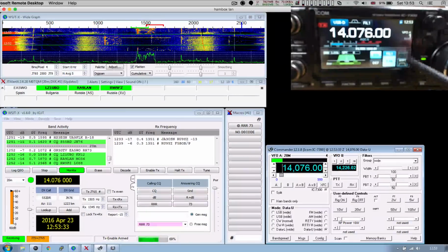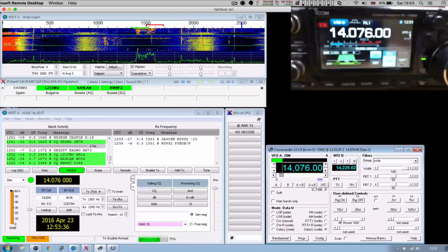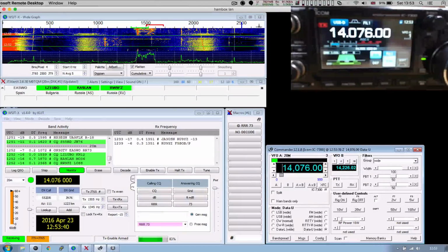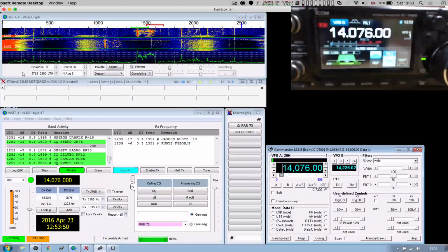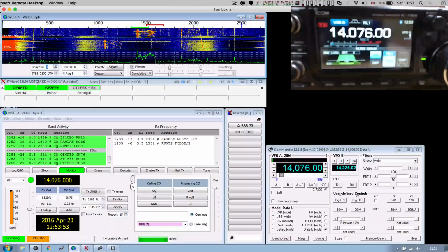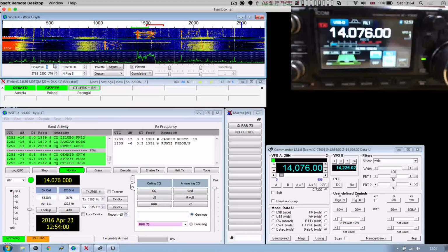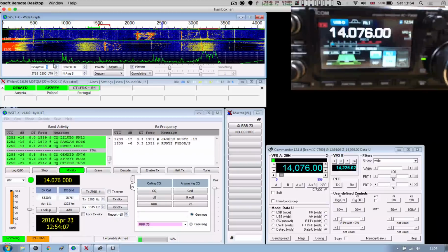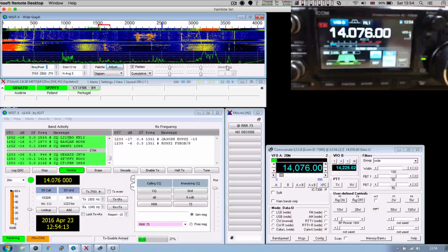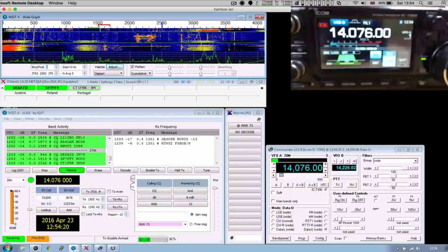Okay, let's do one more trick. At the moment, as you can see, I have the waterfall from 0 to, give or take, 2.75 kilohertz up from the tuned frequency. Now it's worth actually increasing this one. At the moment I don't see too much of JT9 transmissions. What I can do, if I do more bins per pixel, is take it up to 4 kilohertz, give or take. And with the 3.6 filter, as you can see, the 3.6 is roughly here, and it's correct. There is nothing there, except there is a signal right now, which seems to be quite strong. But you can see the shape of the filter.